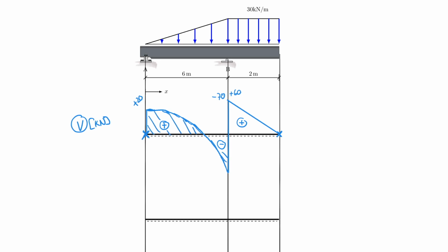So let me shade this. And you can now find the equation to really verify this and to plug in the values for x equal to 6 and x equals to 8 meters here. And then one thing you definitely need the equation for, and that's something I don't give you so that I can really entice you to do this calculation yourself, is to set the shear force function equal to 0 so you can find where V is equal to 0. What is this in meters?